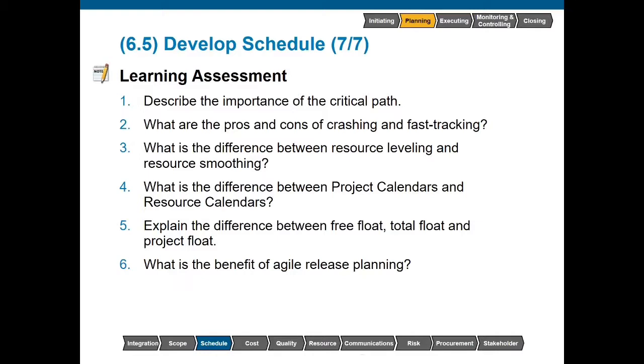What is the difference between resource leveling and resource smoothing? Resource smoothing only allows the activity dates to be modified within the float values that they have. So we're not changing the project duration. We're just making minor adjustments based upon float. But resource leveling will allow the schedule to slip in order to optimize our resources.